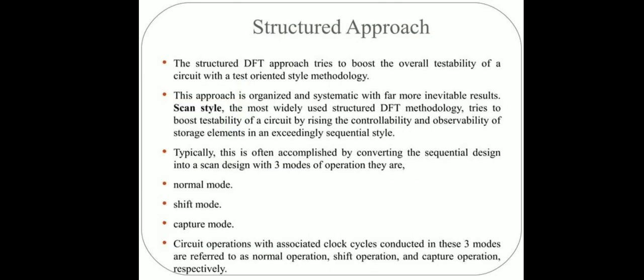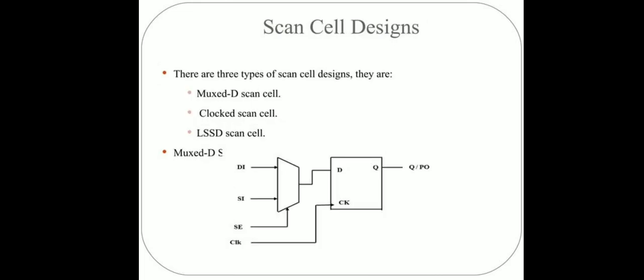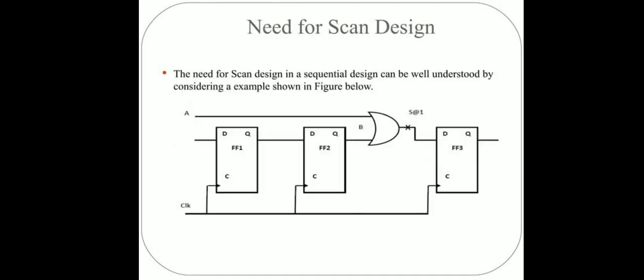The structured approach tries to boost up the overall testability. Testability is mainly designed in, which is done automatically through controllability and observability. This design has three modes: normal mode, shift mode, and capture mode. Scan designs are mux-based and clocked designs.